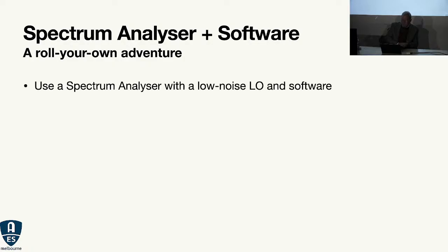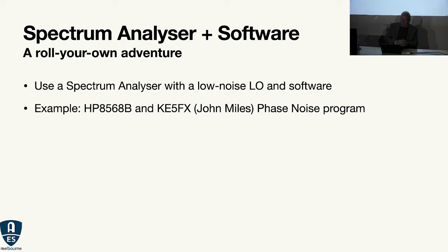So I use a spectrum analyzer. It's got a nice low noise local oscillator, and I use a little bit of software. In my case, I've got an older HP 8566, and John Miles has a phase noise program, which he gives away for free, which is really awesome. A very nice program.